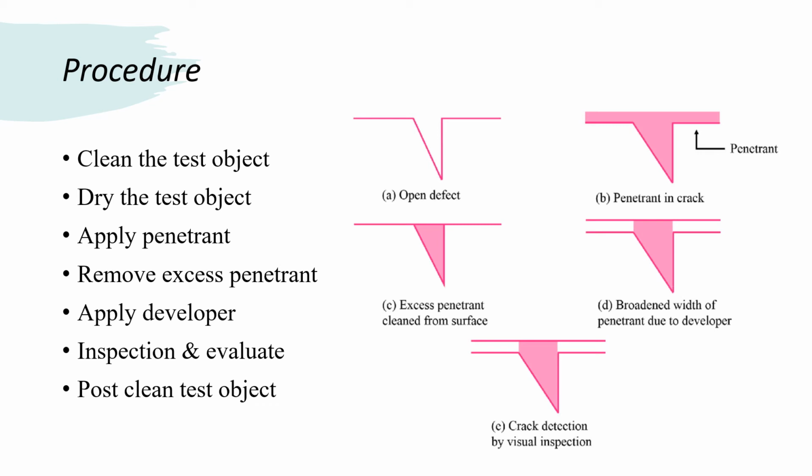On the other hand, insufficient cleaning will leave a background of penetrant on the surface. Due to this, the defect will appear only slightly different from the background area. So this difference in contrast may not be sufficient for the defect to be recognized. Thus, care must be exercised so that neither insufficient cleaning nor over cleaning is done.